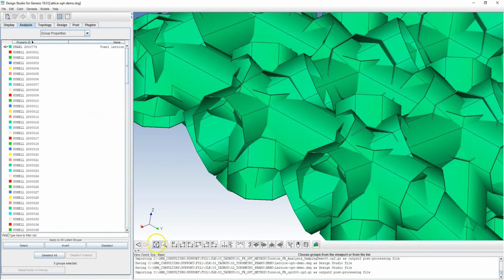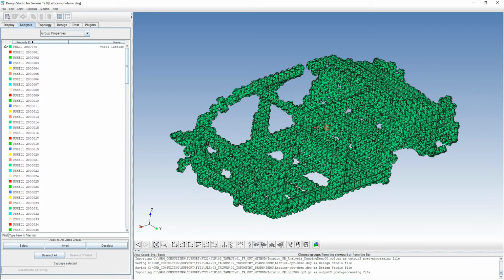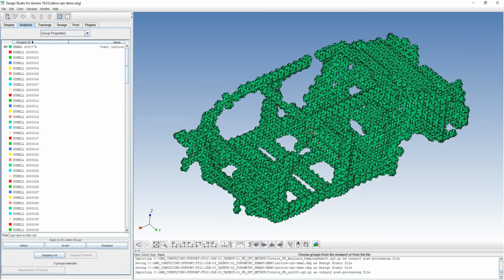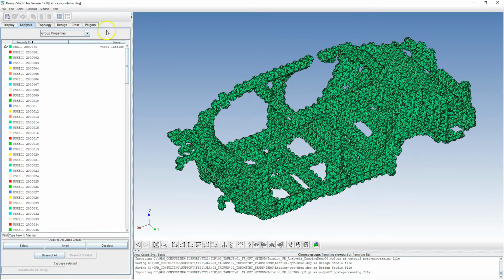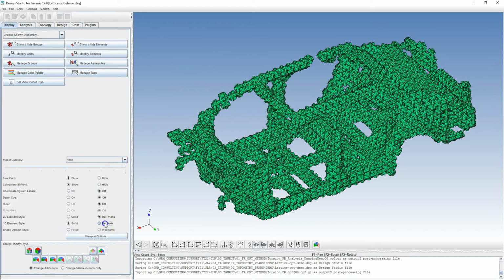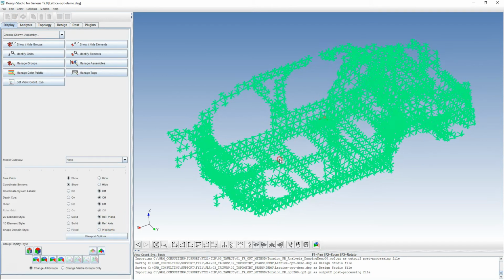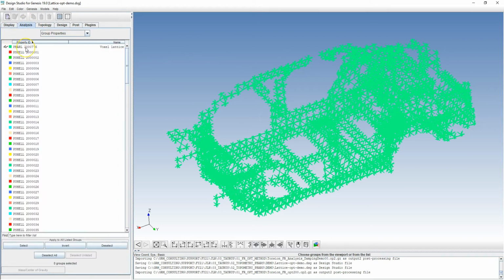Okay, so they're the lattices. They can be created in any tool you like, really. If you've got them from another source, then that's absolutely fine to use those. One note, if you're going to perform optimization in Genesis for what we often describe as bars or beams, they must be bar elements, so that's the PBAR and PBARL formats in place of the PBEAM and CBEAM. And that's because the design data is only associated to the PBAR format inside Genesis.